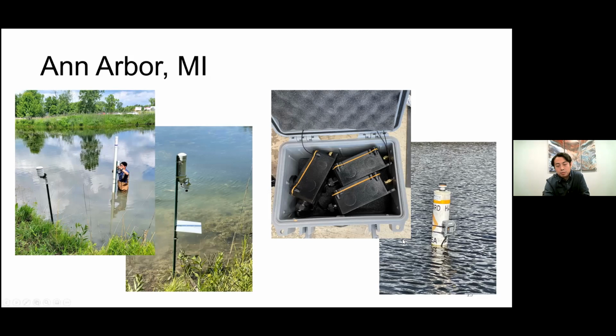There's a pond to the north of Ann Arbor. We were able to install similar types of sensors where we tied 3 temperature sensors together, communicating through the same transmission module you've seen earlier, and connected that to a smart buoy. That enables us to measure the temperature profile in the pond itself. We're hoping these can help measure hypoxia someday, for example, using the temperature profile measurements.